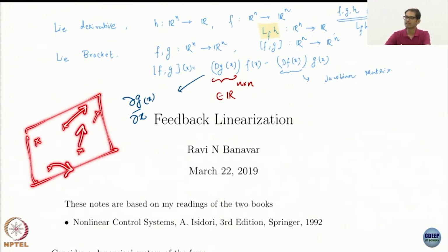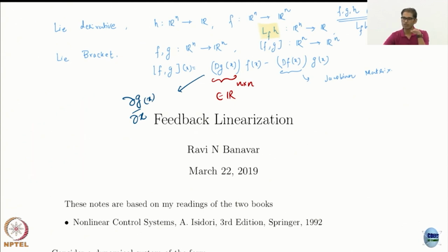It actually tells you in what directions the system can move. We don't talk about controllability again, but it's well understood that if you have the drift vector f and the control vector g, then you can also move in the f, g Lie bracket direction. So I got a new direction to move in. It's almost like saying I have a car, and I can turn right by 90 degrees or I can go straight.